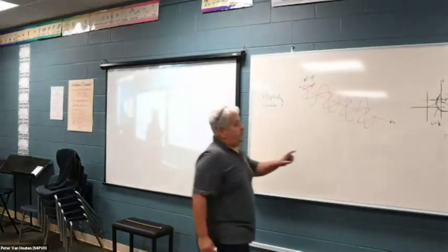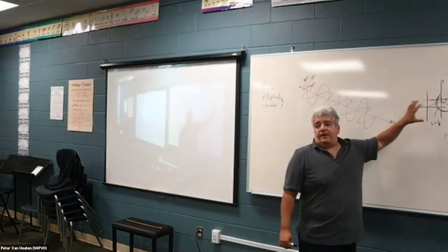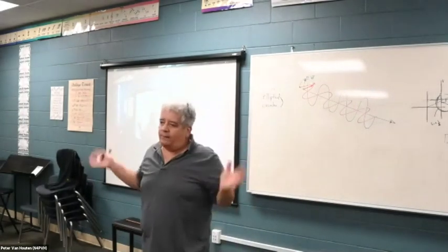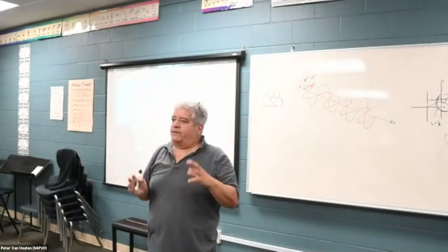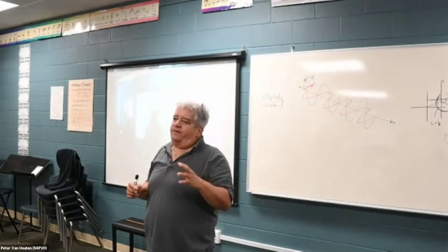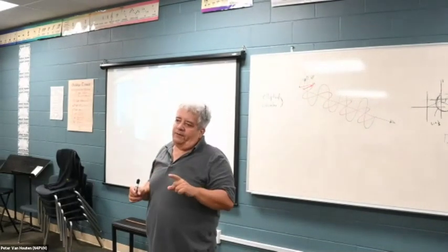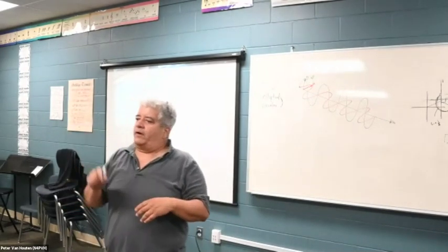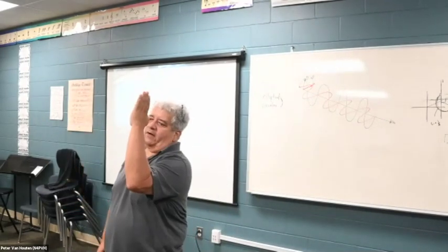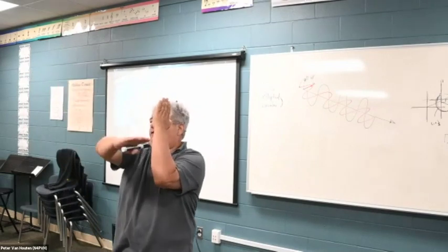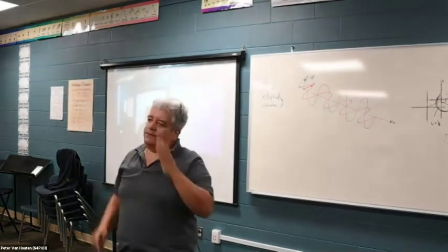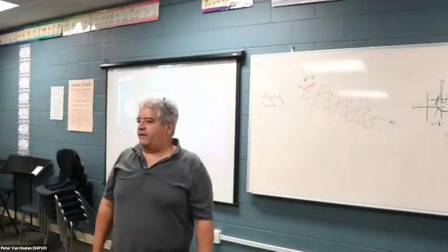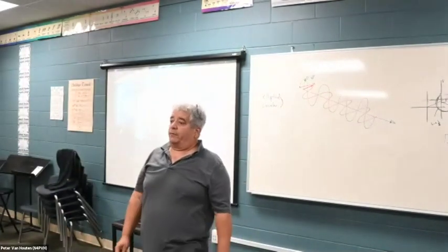One thing is that if you are a circular polarization receiver and a wave is vertical or linear polarization, it doesn't matter in which orientation it comes, you will receive it anyway, but you are losing 3 dBs. But 3 dBs is better than not having circular polarization, where you are oriented like this and the signal you're receiving comes like this. The difference can be 20, 30 dBs. So that's 100-fold, a 1,000-fold. You're not going to hear it probably.